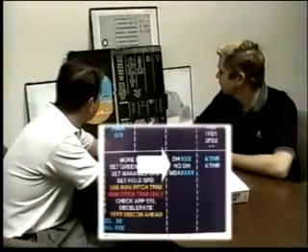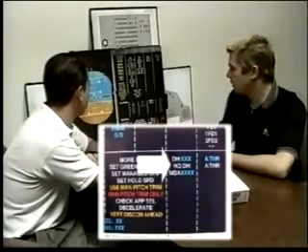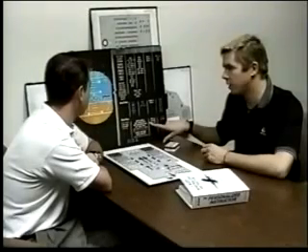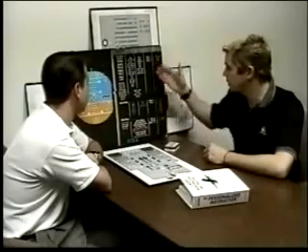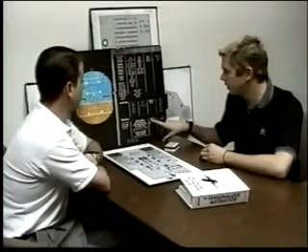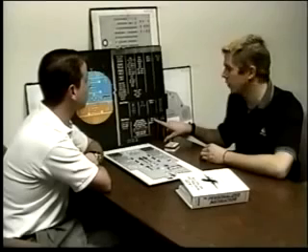So, Cat 3 dual, we can shoot a Cat 3 autoland approach. Cat 3 single, we can shoot a Cat 2 autoland approach. Cat 2 means we can shoot a Cat 1 non-autoland, and Cat 1 means the same thing. Cat 1 non-autoland. What about the decision height, no DH, and MDA? Decision height and MDA, they had good intentions, but decision height truly means radio altimeter, and MDA means barometric altimeter. Now, the intention was that these were going to be for all the decision height approaches, but unfortunately, the only approaches we reference an RA on are the Cat 2, Cat 3 approaches.